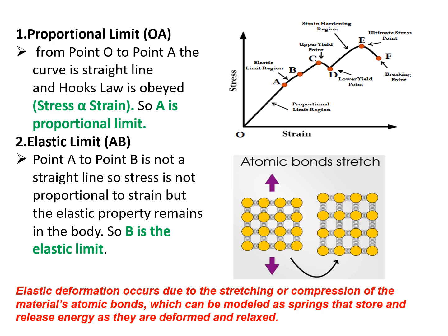Now the first one. I start that graph from this particular point, O, and O means there is no stress, no strain, meaning the applied load is 0, so we are not getting any deformation. So that is the point O. Now when we get this graph from the machine, we have to talk about its various salient points.